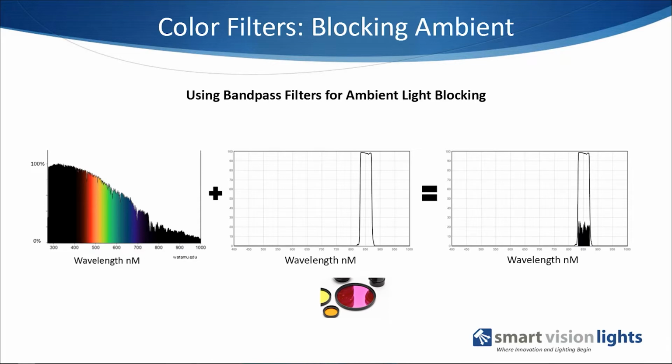But if you're dealing with sunlight, it is most common to use the 850 area. Some people also use the 960 nanometer, which is also a deeper color of near infrared that we have available, but it's important to note your camera is less sensitive as you move further and further out. So unless you have reason to move that far out, people typically use 850 when blocking sunlight.